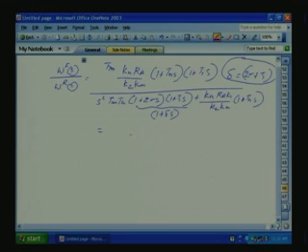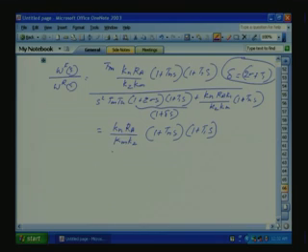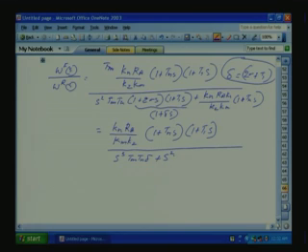So, the final transfer function, if you properly simplify this one, will be Kn Ra by Km K2 into 1 plus Tn s into 1 plus T1 s divided by s cube Tm Tn delta plus s square Tm Tn plus K0 K1 Tn into s plus K0 K1. So, the denominator, if you see here, is a third order one.